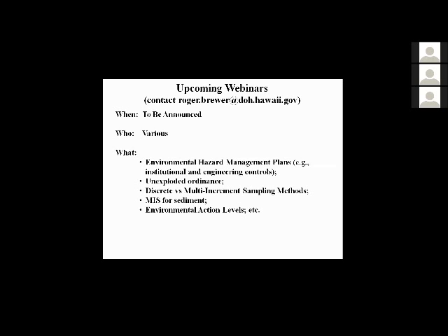We had some questions about reporting the data as a concentration, as we did with the mass-to-concentration tie-in. That is an exercise that we can provide on a site-specific basis, where we have the measurements by passive soil gas as well as active soil gas, establish that correlation for the site, and then apply it to all the sample locations to derive what the concentrations were at each of the locations. That is data that can give you guidance still on the concentration. It's not a concentration that's going to be accepted at this point by regulators as a definitive concentration.